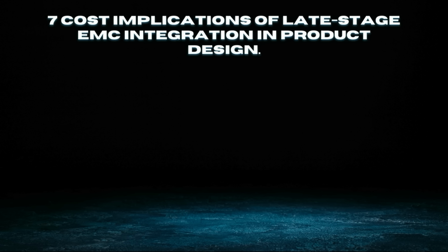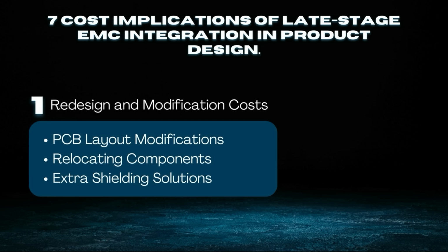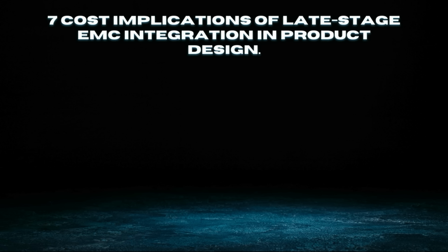Here are 7 cost implications of late-stage EMC integration in product design. Let's explore the key cost factors. 1. Redesign and modification costs. Late-stage EMC integration often requires extensive redesign efforts, which can be both costly and time-consuming. Changes like adjusting PCB layouts, relocating components, and adding shielding solutions contribute to increased expenses for materials and labor.